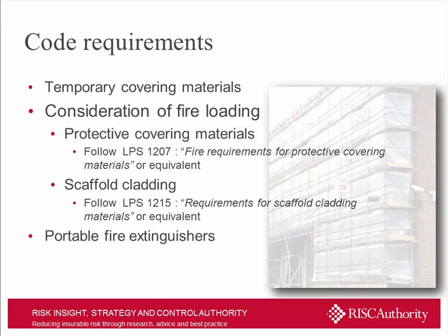And then at the bottom there, reference to the need for portable fire extinguishers. Again, if you consider why we have fire extinguishers in buildings, the government would tell us that they're there for life safety purposes only, should you need to tackle a small fire to affect your means of escape. However, I think we all recognise that in certain circumstances people will use them to extinguish a small fire before it becomes a large fire, and so having a suitable number of appropriate fire extinguishers, effectively located and properly maintained, is a great way of providing that first line of defence.